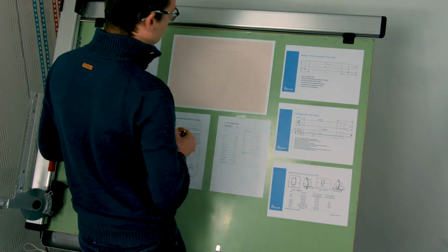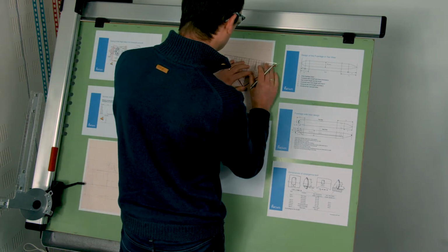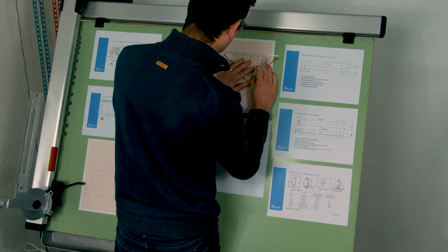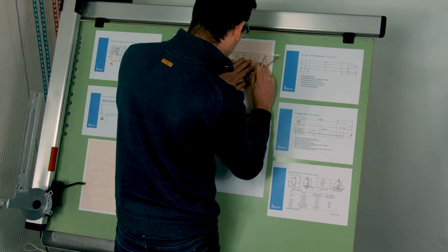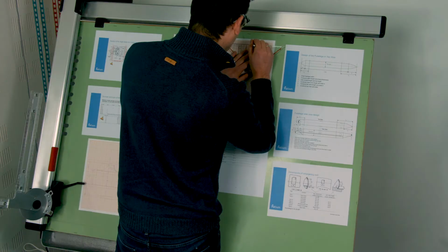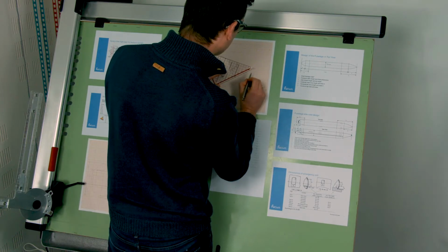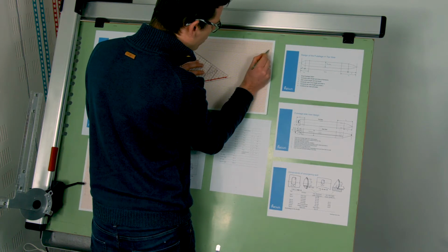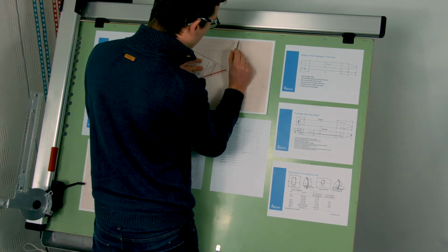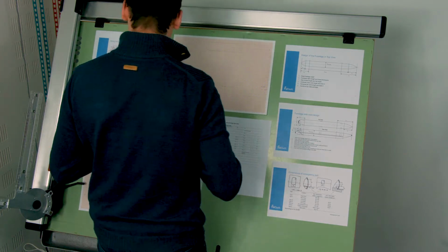All right, now to help me out a little bit, to draw this tail cone, I'm making a very thin extension of this line just to make sure that whenever I draw this tail cone, that it's not gonna go out of this bound. Yeah, and that's just to give me a little bit of a guide, because I now need to make a curve all the way up to the rear end of the fuselage. I don't need a protractor for that.